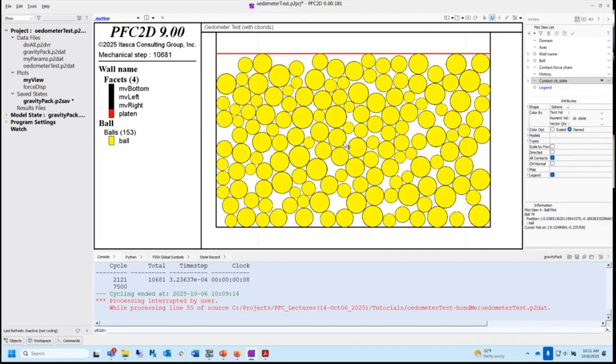We saw that for the granular case, which is why the coordination number keeps getting higher and higher for a while. So if I take the initial state and bond it, I get a certain amount of touching particles that I bond. If I squeeze it for a while and then bond it, I get more cement, I get more bonds.